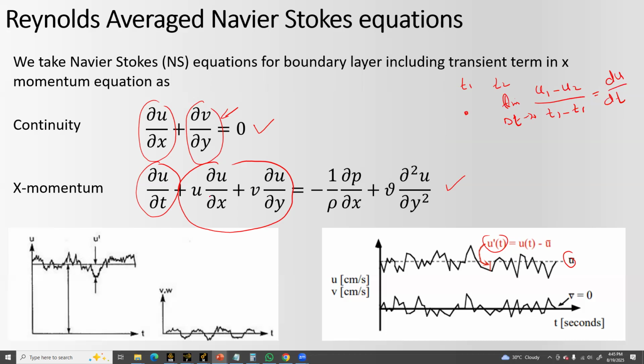But this other term is a convective term. What does it mean? It means that we have the velocity at one point, at a location x1, where the velocity is u1. The second point is at x2, where the velocity is u2. If there's a difference in the velocities, we can determine the velocity change as u2 minus u1, or whichever value is greater you put first, divided by x2 minus x1, and this is delta x.